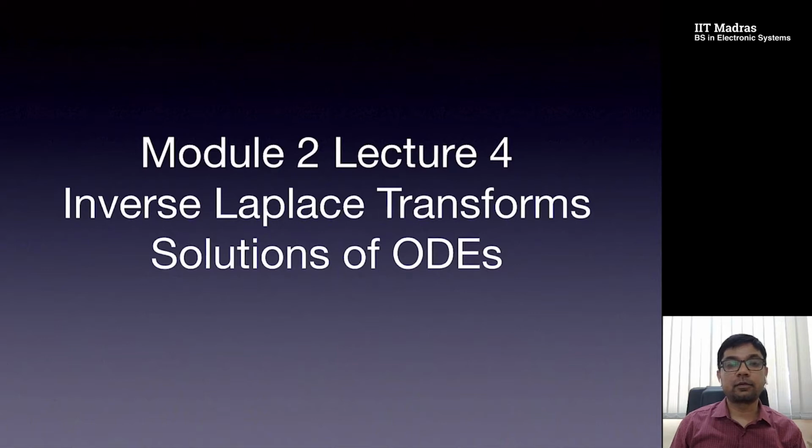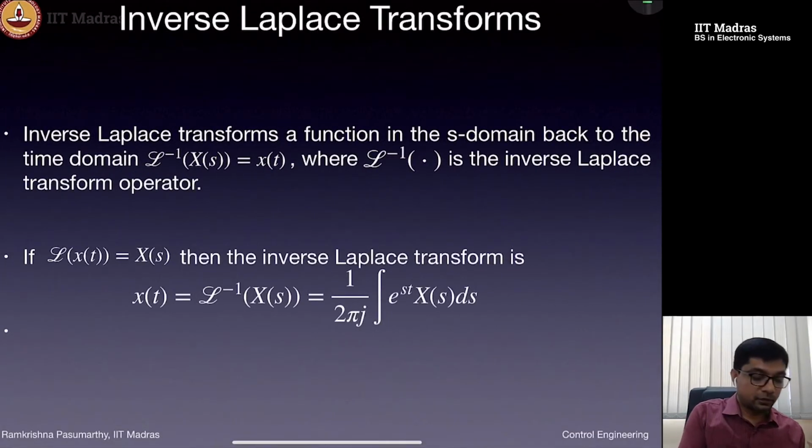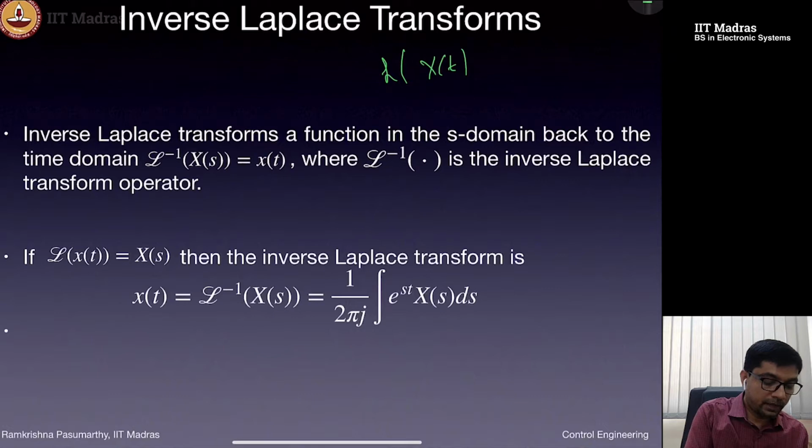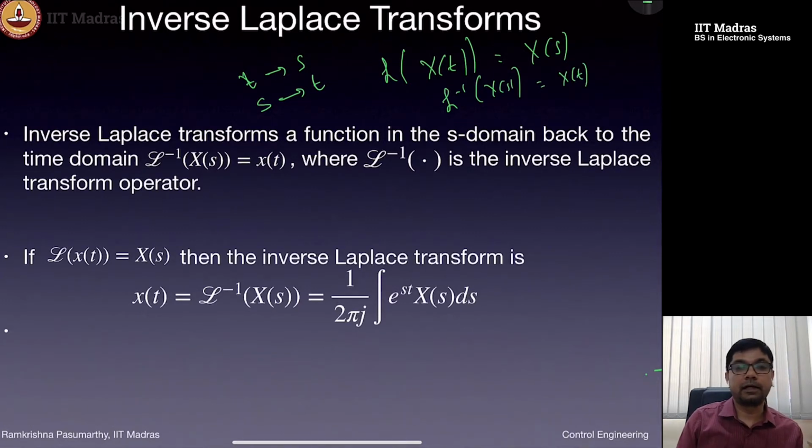In this lecture, we will talk about inverse Laplace transforms and how the entire domain of Laplace transforms helps us understand or solve convolution better, or even solve simple ordinary differential equations. So the inverse Laplace transform: I have a signal x of t, I do L of x of t to give me X of s. So if I am able to move from the t domain to the s domain, I should be able to move back from the s domain to the t domain. That is the notion of inverse Laplace transform, denoted by L inverse, which will give me back the original signal in my time domain.